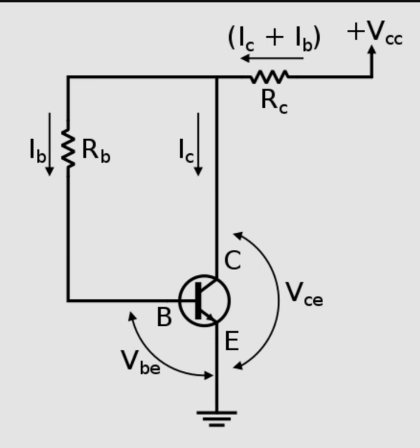So as usual, you have an NPN transistor with the collector, emitter and the base pins. The base emitter junction is forward biased. The base collector junction is reverse biased to set the operating point, to bias the transistor in the active region, and the resistors RB and RC are used to set the operating point of the circuit.